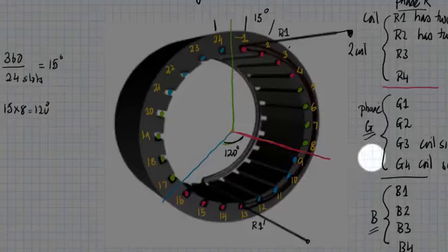Right, so you have 8 slot separations here, so that is 15 degrees. Similarly, the angle between these two is, you have half here, so 1, 2, 3, 4, 5, 6, 7, and then another half here and half here, that is 8. Therefore this angle is also 120 degrees. Similarly, you can show that that angle will also be 120 degrees.